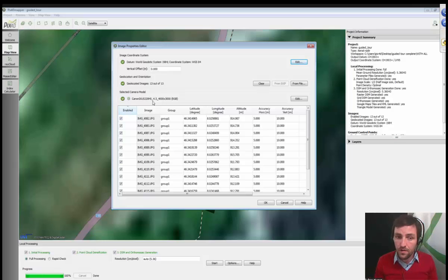However, to be able to perform this optimization properly, the software has to start from an initial parameter. If the initial parameter is not too far from the real solution, it's going to process very nicely. However, let's say for a camera that has an 18 millimeter focal length, if you input 3 meters as an initial guess, the software will very likely end up with a failed processing, because the initial focal length estimate is way too different.